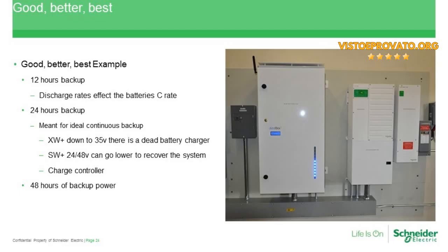If you do decide to add more solar at some point in the future, or want to do a battery-based system, again, to requalify for that tax credit, you do need to bring more solar in. Definitely check with a tax expert, but you can't do it without doing solar. So if the customer is looking at doing a battery retrofit, the upside is that a little more AC coupling is going to be fine, and just make sure that you're sizing the inverter for that upsized system.